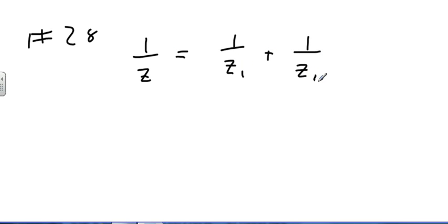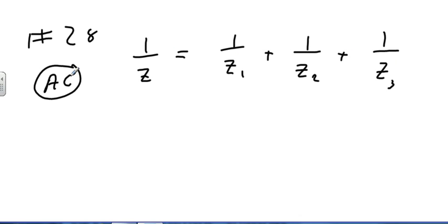All right, now, we use Z for impedance as well. So instead of using R, we use a Z: 1 over Z1 plus 1 over Z2 plus 1 over Z3. And we use a Z for impedance, which means resistance in an AC circuit. So it's just a vocabulary thing. Resistance is a DC thing. Impedance is an AC thing. They're the same, but they are different.